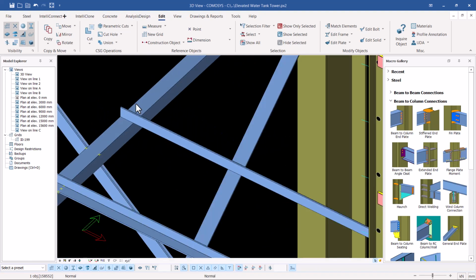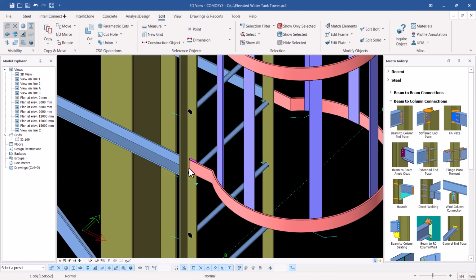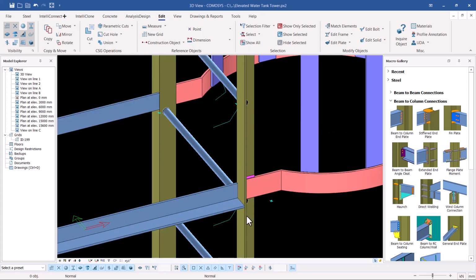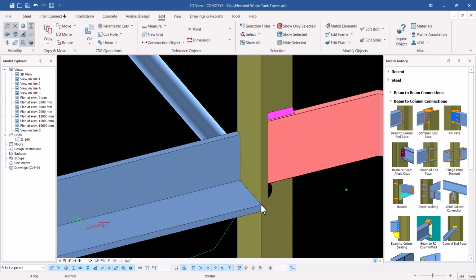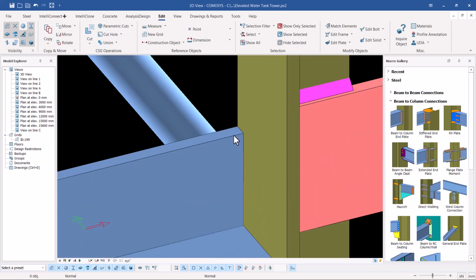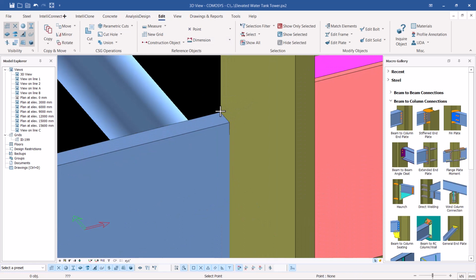Creating a point for any location should not be a very big deal to worry you. So let me just pick my point of rotation and that. So I want to create a plate here that will be welded to this member, and that will aid in bolting this member to this. So let's create the plate there, and creating the plate will need some points to help us in creating the control plate. So I'll come to points here and pick on the point, and I'll snap on that spot there at the edge of that member, right click.